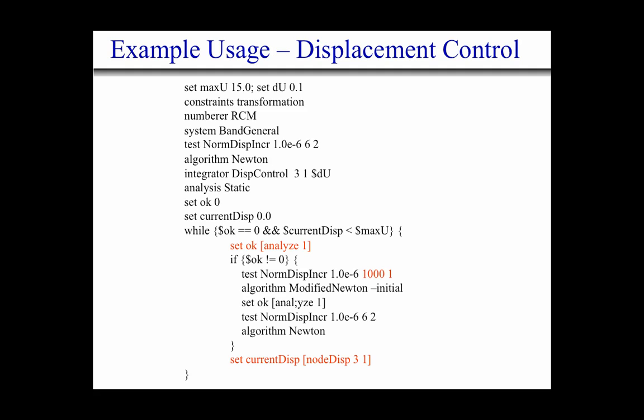So from this 1 you'll see whether this is working, or if you need to up this to 2,000, 5,000, 10,000. I typically stay in the 5,000 to 10,000 range. I've never needed 100,000 iterations, but then I haven't dealt with models over 100,000 degrees of freedom. When you get to really, really large models, this number might need to be really large.